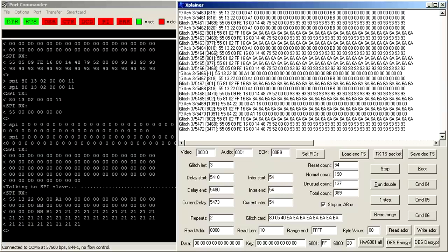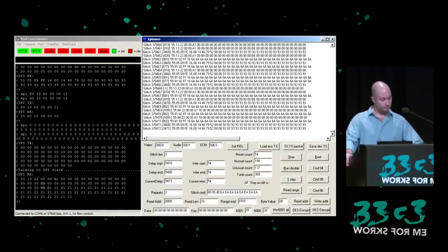There is a 2 kilobyte area of ROM that, if I attempted to read it, caused the chip to reset. This area of ROM contains the personalization routines that are never normally used after the device leaves the factory. There's also protection against modifying the seed keys in RAM. Trying to store a value to these memory locations appears to do nothing. There are specific addresses within RAM that can't be read or the chip will lock up. These are clever traps put in place as a security measure.